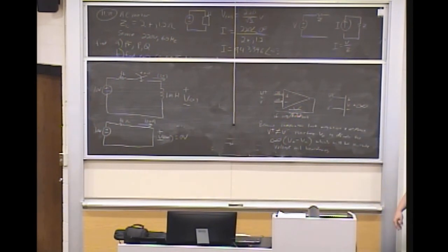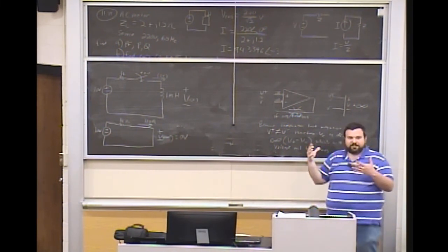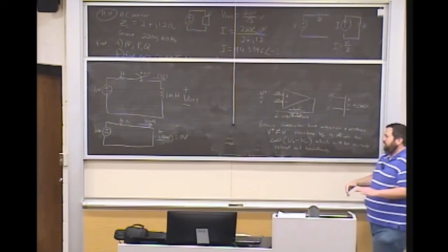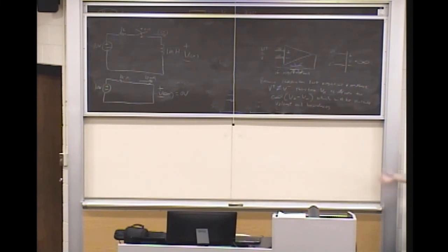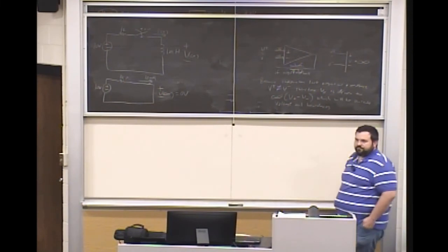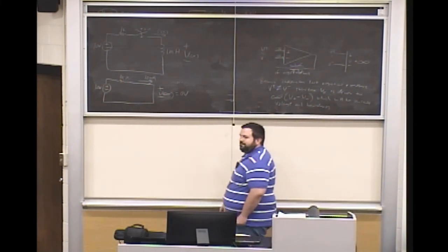The other is whatever you expected to get out at 50 degrees Celsius. If your voltage was greater than what you would get at 50 degrees Celsius, it's saturated. And if it was less than what you got at 20 degrees Celsius, it's saturated at the other rail. Does that make sense? Does that help?